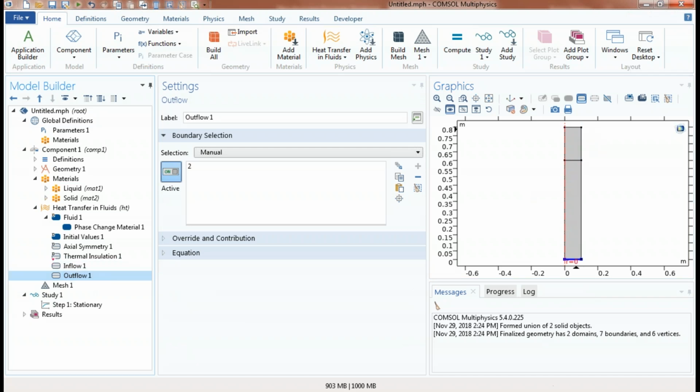Now on the solid surfaces, I'm going to have some heat loss to the mold here on this boundary, some kind of steel mold. Then on this boundary here, what I'm going to do is have heat loss through radiation to the ambient environment, but also some cooling effect due to some coolant being sprayed on the material.